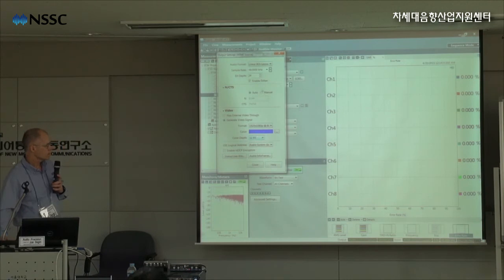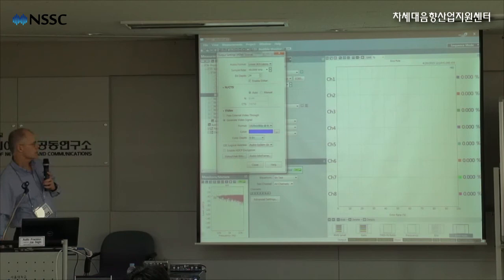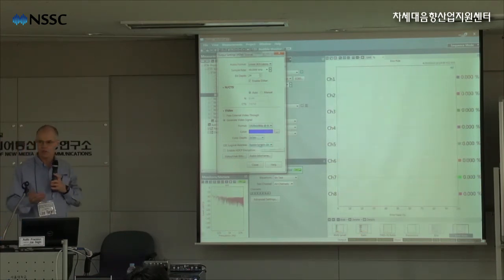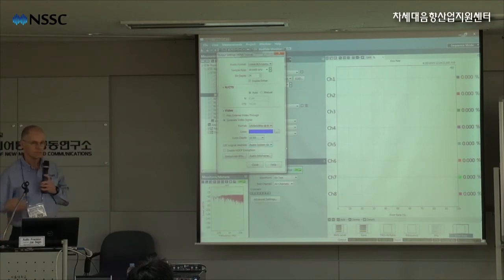We connected up his device and did this bit accuracy test, and it would pass the test with 0% errors at 8-bit color resolution, but when we went to the higher video formats and the higher resolutions, it was no longer bit exact. That doesn't mean it's terrible, it just means that it's not bit exact, and if it's not bit exact, then you need to do some diagnostic testing to figure out what's going wrong in the signal. And there are some tools that we have for that.